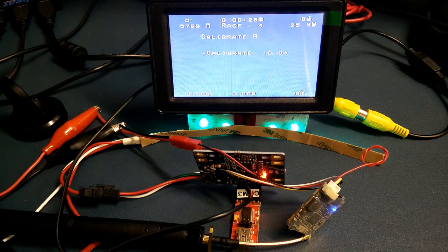There's also ampere current measurement adjustment, so you can calibrate that. If you find that the KISS ESC isn't quite accurate enough, you can fine tune it there. Same as the milliamps, so they're separate just in case for some reason one of them is out and the other one isn't quite as far out for some reason.